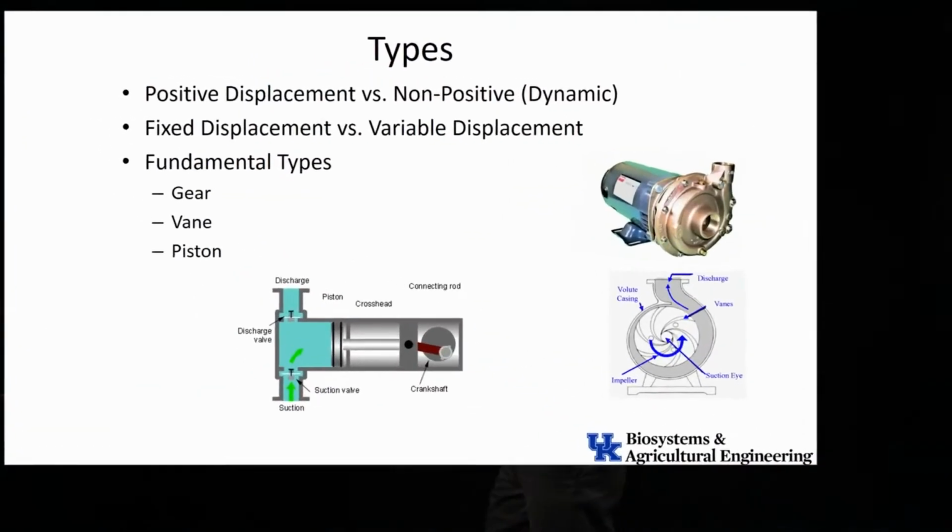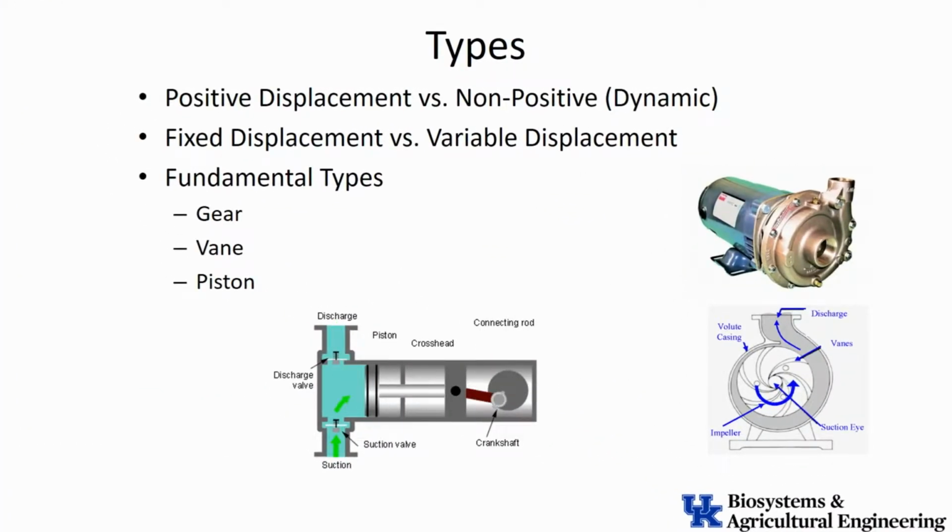So if we can zoom into the slide, the JIC symbol for a pump, and you saw it earlier on that earlier drawing, it's a circle with an arrow coming out of it. So again, it kind of shows you, a lot of these pumps are circular like that. There's an arrow coming out of it, and the drawing could be as simple as that. Sometimes we will add a shaft on it to show the rotation. So we'll put a circular arc arrow around that shows that that's the mechanical shaft providing the rotational power. And there's a lot of variation to these, and I'll show you these as we go through, but this would be a pump that's pushing fluid out of it.